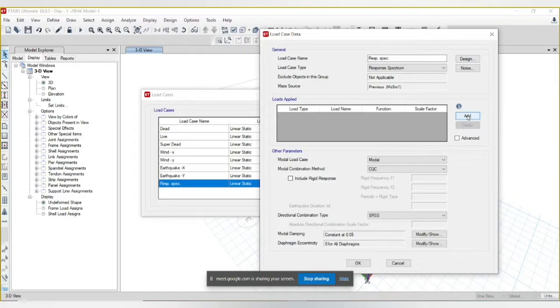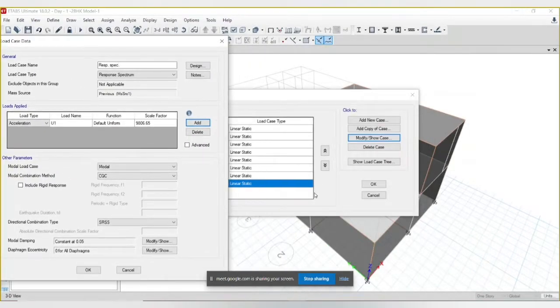You should add the loading type. Do you want to load the ground? The earthquake force can be applied in two methods. One is vibrating the ground, or you can vibrate the structure by using some load. Currently, you will be vibrating the structure from the ground.